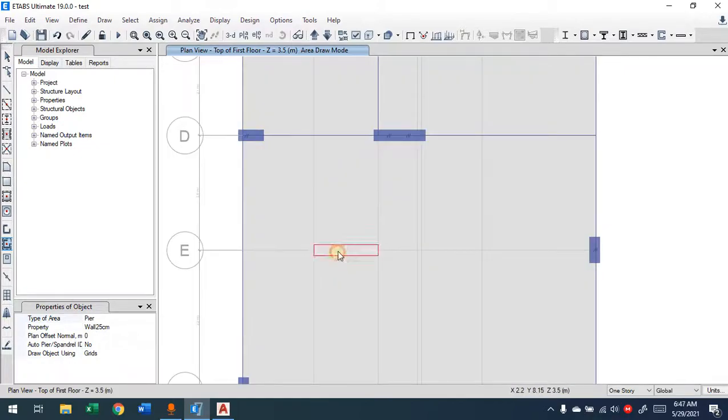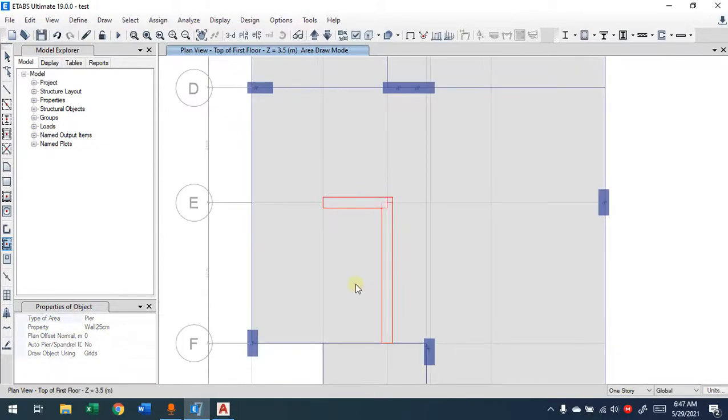You just simply click on the grid here, and the grid here. That's it. We know the quick toolbar, how does it work? Mainly working with the grid. So in between grids, over the grids. That's how the quick toolbar works. Any quick option that we have here normally follows the grid line. So if you don't have grid lines, you'll not be able to use the quick one.